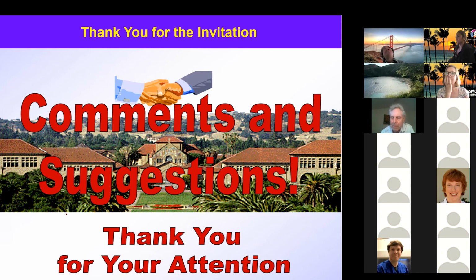One of the reasons we're interested in sensor data recovery algorithms is to go back to cross-validating the sensors among themselves. I illustrated that when a sensor goes down, you can reconstruct its data. But you can actually apply it the other way: can I use other sensor data to cross-check the sensors themselves, to see if they are outliers based on the data set you collected before? That is one possibility to make sure, first of all, that the sensor data is good.